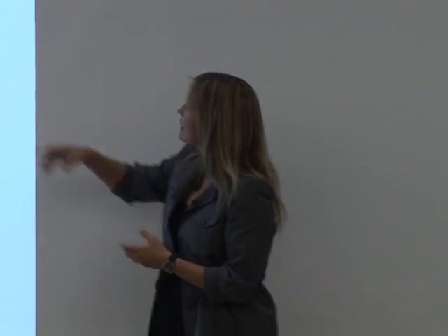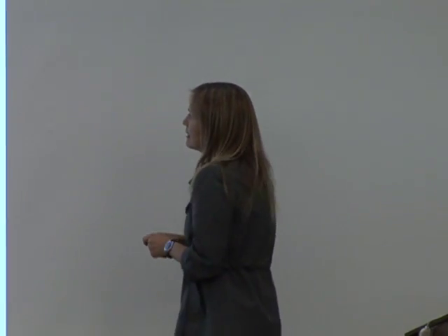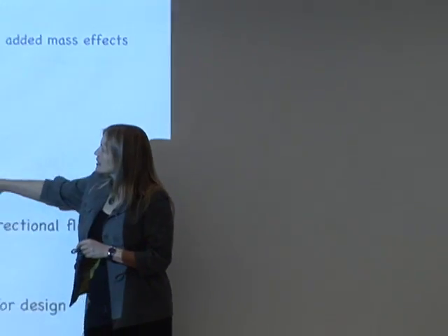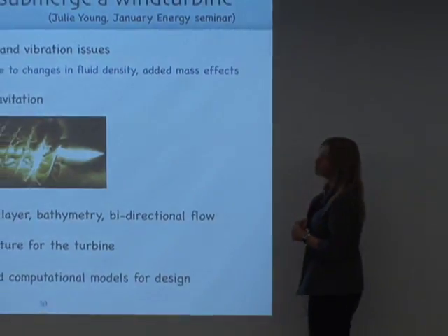In air, you can neglect these things, but in water, you cannot because of salinity. So when the blade turns, it goes through gradients of density, and that gives you forces on these blades, extra stresses that are very hard to deal with. And then you have tremendous added mass effects that are much stronger, of course, when you're displacing water than when you're displacing air.